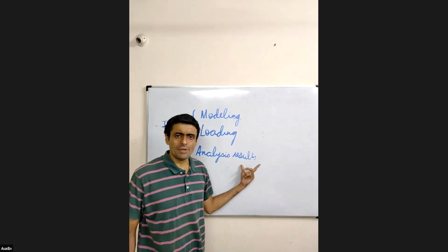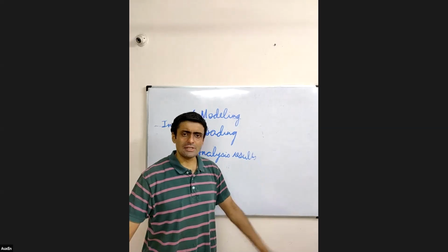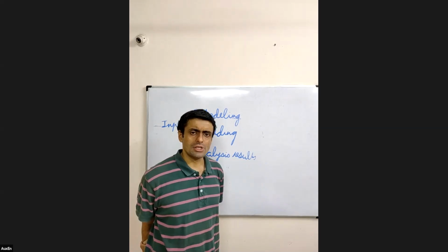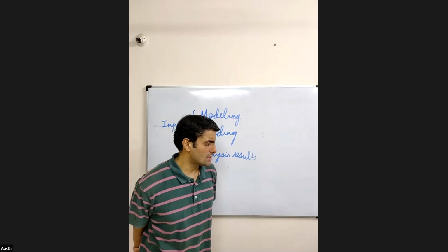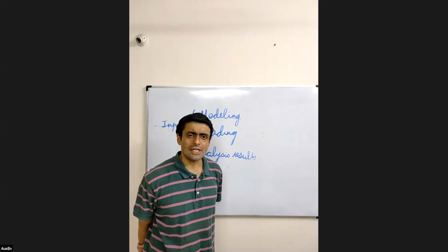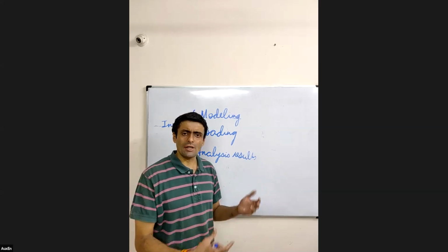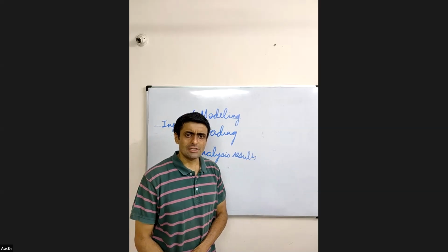The third step would be that we carry out analysis. By carrying out analysis, I mean that I would be getting bending moments, shear forces, compressions, tensions, torsion, all those actions, and deflections, and my computer would be internally solving to give me all these analysis results.